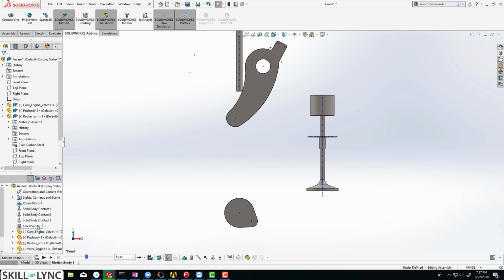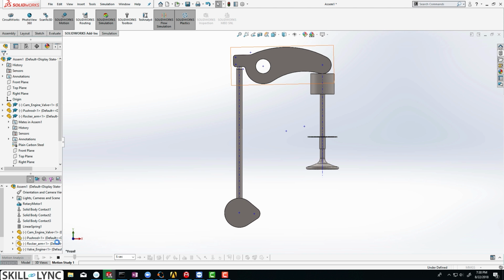If the spring is not stiff, then it can easily be pushed in and it's not going to offer any resistance. So now you can see that when we assign the right value of stiffness, it pushes the rocker arm back in the desirable way. So it's very important to add the right mechanical properties and material properties to make sure that the results are accurate. Or actually, what you will be doing is following this particular video, and making sure that you get some results.